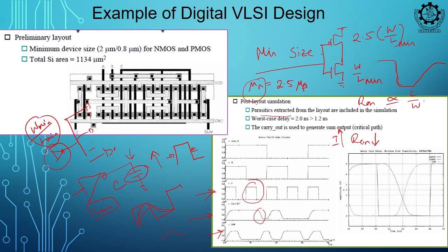In digital circuits, your job is to have more number of transistors, right. So, to reduce the area we use minimum L, and this is another reason, R on.